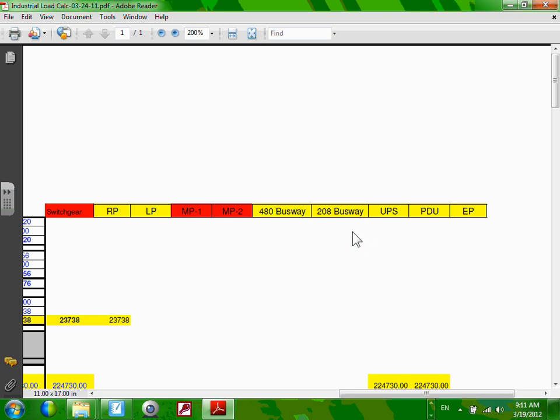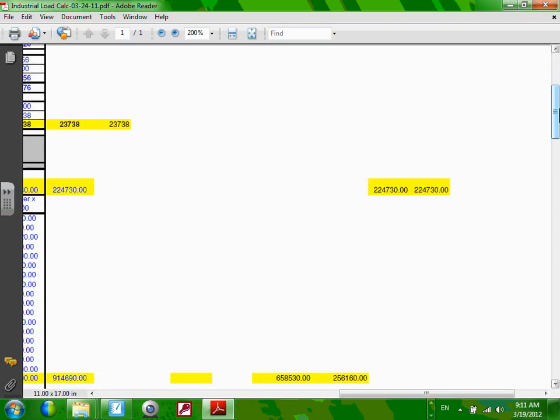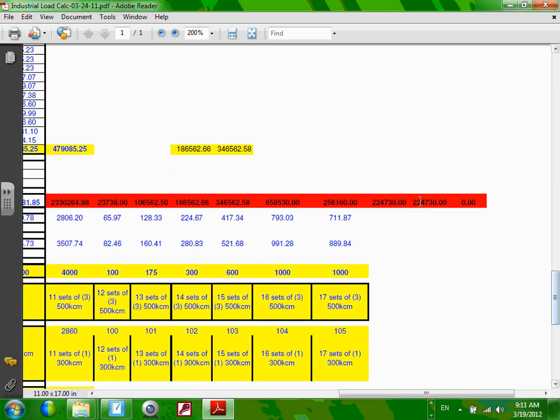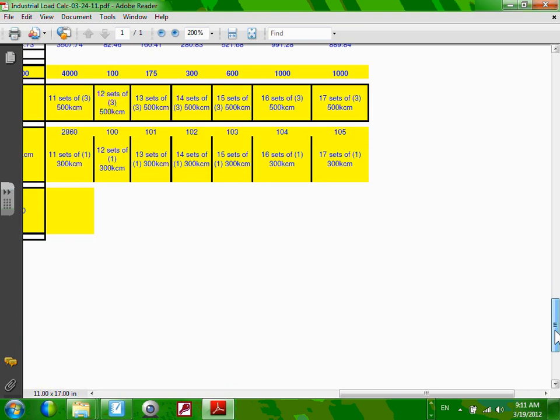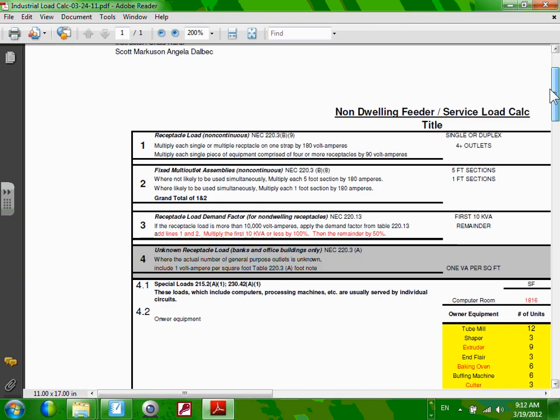What I asked the students in the past is when you do the calculation, you grab, like under PDU, here's the load that's going to be under PDU, expected loads. And you can go all the way down, and then this is where you can size each one of these from one calculation. Look at it. I know I don't want to make it a load calculation, but here's all the most important things, the steps. You look at these steps, these are accurate steps. You guys are going to build it, make sure you reflect it in your load calculation.